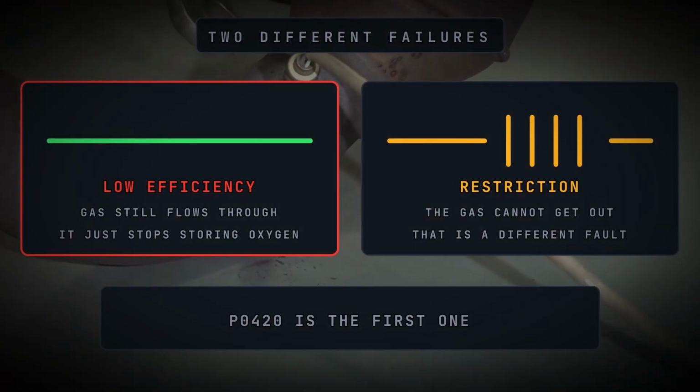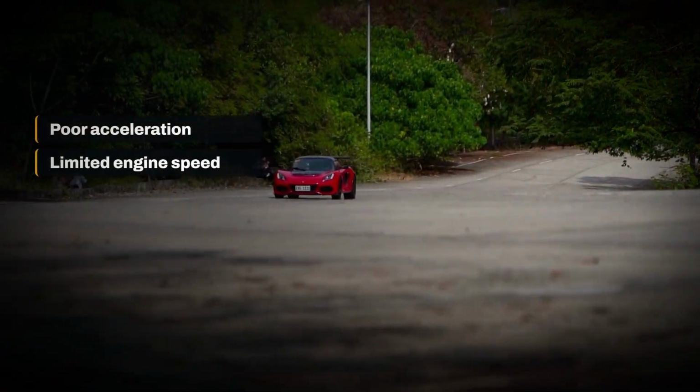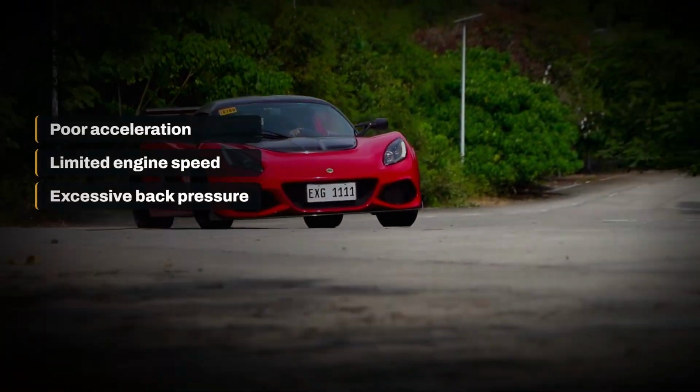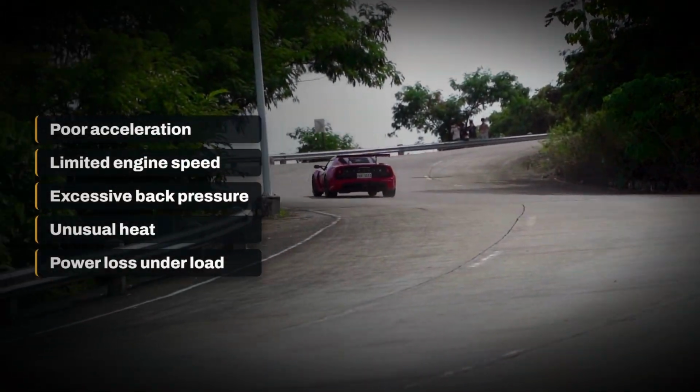A restricted converter is different. It may cause poor acceleration, limited engine speed, excessive exhaust back pressure, unusual heat, or a loss of power that becomes worse under load.